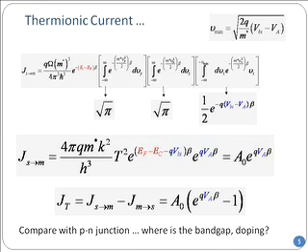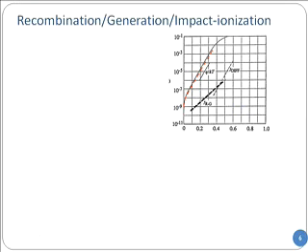Deriving an expression, these are not complicated things, but you should be able to come back and say that if I change my material, let's say somebody says I don't have aluminum deposition, I want to do copper deposition today for some reason, you should immediately be able to say what it is in this expression that you are modulating. Of course, you cannot modulate V_A, that's your AAA battery from outside, but you can modulate the constant up front. That's your design of the devices.